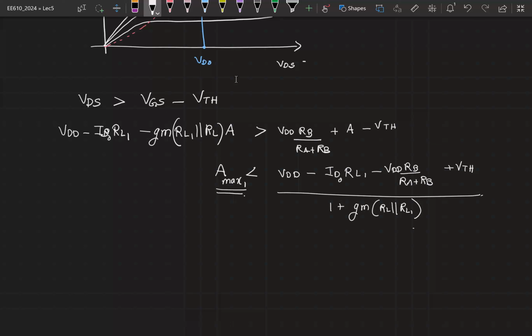your transistor is entering into triode region, right? What is so wrong if the transistor enters in triode region? Why is it so bad? What changes? Gain will change. How does the gain change? Transconductance value is... So we already saw that the GM value is going to be much smaller in the triode region than in the saturation region. So that is one part. Your GM is going to reduce, which means your gain is now going to be smaller. What is the other issue?